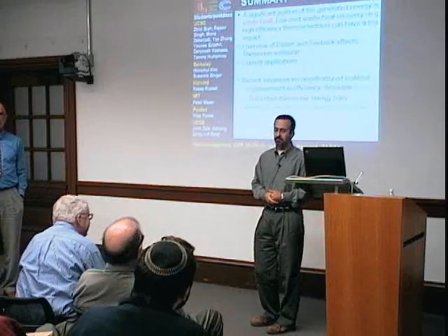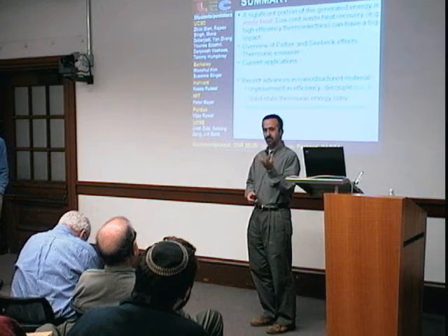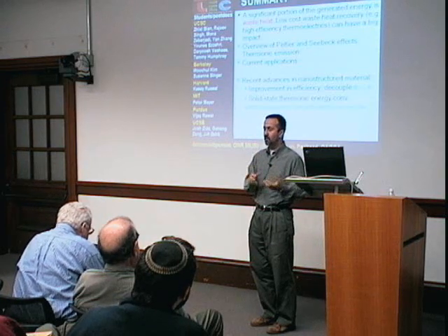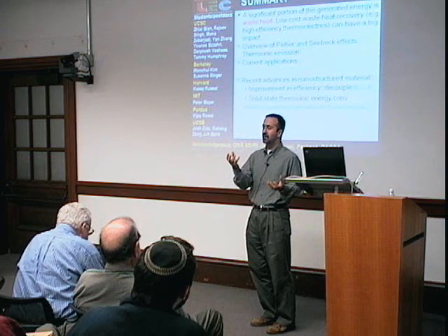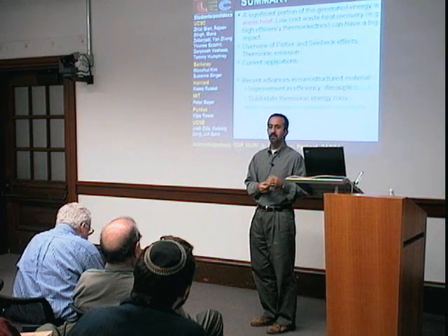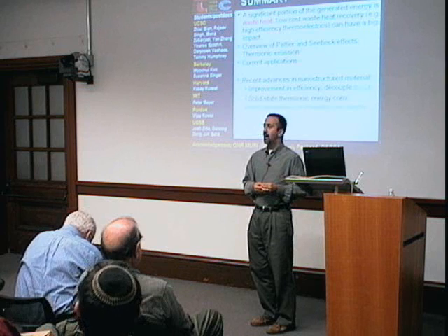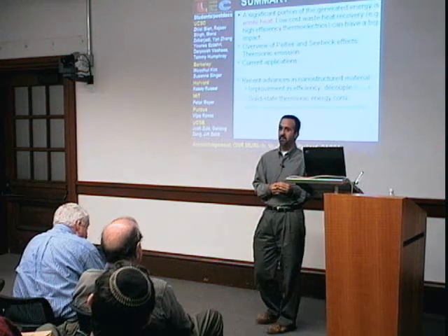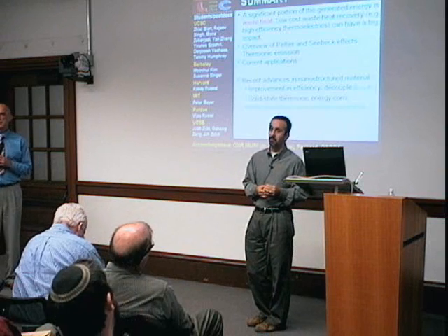That's a good technical question. In the case of vacuum devices, electrons are emitted from a solid into vacuum. Even if you have a material with a small work function, as soon as they come out, the negative charge of the electrons in the vacuum creates a potential barrier for additional electrons to come out. That basically limits the working temperature of vacuum devices to more than 1,000 degrees Celsius. In the case of solid-state devices, we don't have that problem. The barriers are much thinner, so the space charge effect is not the main factor. Our key factor is to have a material which is a good electrical conductor and a bad thermal conductor.